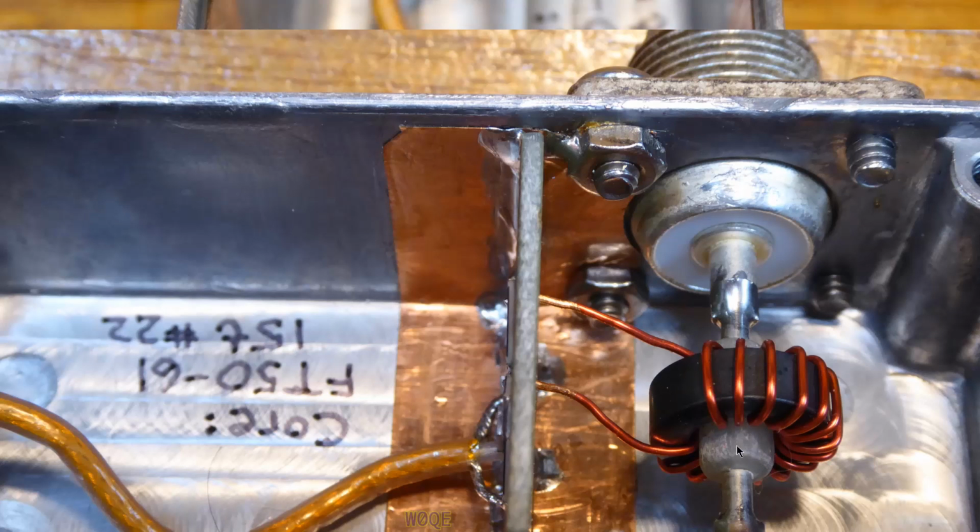This piece of plastic is a fairly low dielectric constant. It turns out plastic is kind of an interesting material. You want an insulator in here, and this insulator needs to locate the toroid. But in the process of locating the toroid, the plastic a lot of times has a dielectric coefficient of 4 or 5 sometimes. So Teflon is the best that we can generally come up with. But Teflon is not an easy material to make stick on wire and stuff. It doesn't stick to anything. But you can jam it in there, and it's good enough.